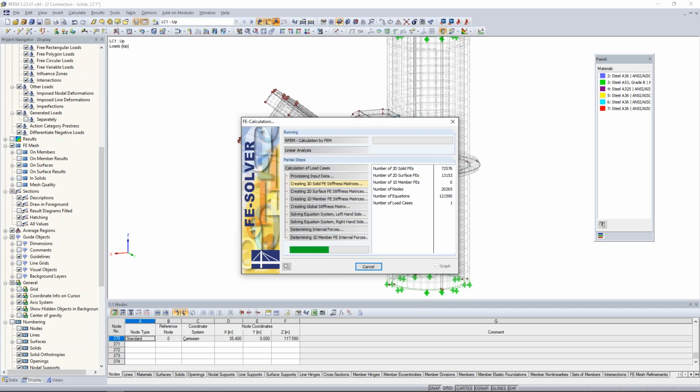Now, for this particular load case, everything is linear. Even the load case itself is a linear analysis first order, so it should solve rather quick here and will eventually be presented with our results graphically within RFEM. Also, no material nonlinearity shown yet. We'll get into all of those in just a minute.